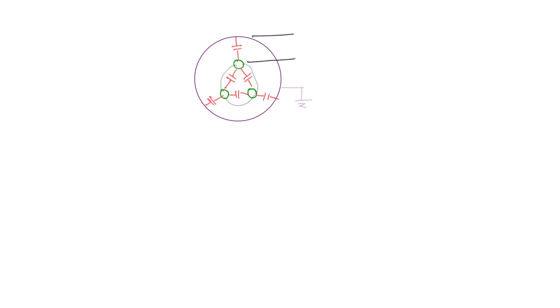So now the question is, how do we find the sheath and the core capacitances? How do we measure it practically, right? Here you have to make two different connections and measure the capacitances. So here this is the core to core capacitance, and here you have the core to sheath. Now what is going to happen? You have to connect all the cores together. Okay, that means basically you are short circuiting the cores. So here this is grounded, right? Now what will be the capacitance when measured across each core and the ground?